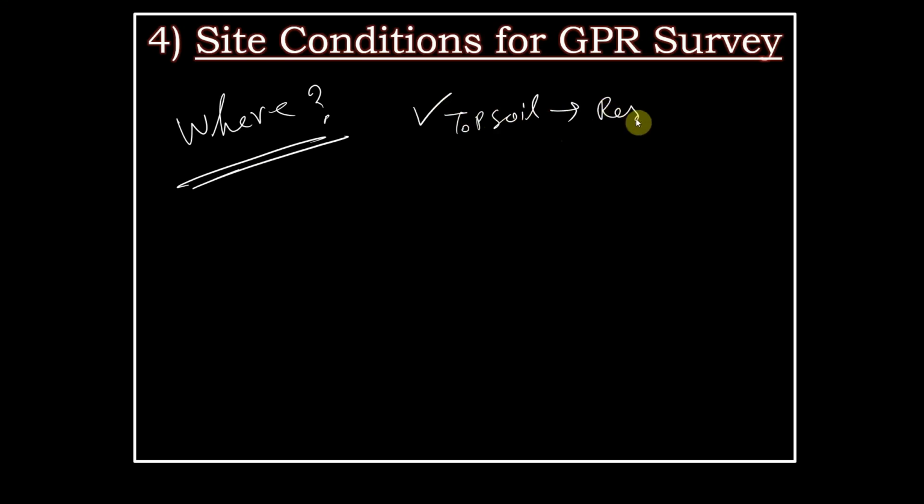Now the most important point in this discussion, everything is important, but the most important is you have to determine where to survey. Okay, so this is interesting. Listen to me. Where you can do a GPR survey, which study site you should consider. So first, keep in mind that I have mentioned the topsoil or the overburden should be resistive